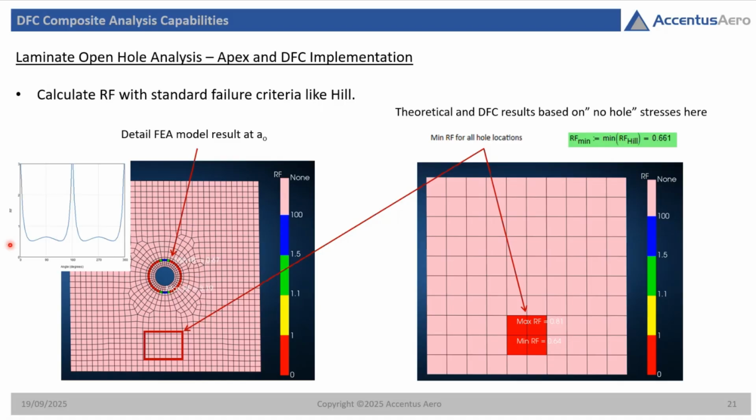And you can see it ties up very nicely with our predicted RF distribution. It goes from high to failure, with a minimum RF at around 40 degrees. That's typically what you see here. Then for these areas up to 180, you get the problem areas, and then you just repeat that. So there's good correlation between the FEM result and what we get with the theory.